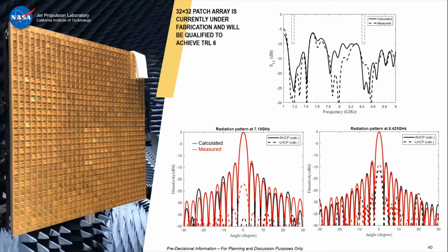We did not see any discharge, or the only discharge that they saw, they couldn't tell if it was only noise or actual discharges. That was actually the first time ever that they tested a piece of hardware and saw such low discharges, and that's why they couldn't tell if it was noise or not. So our antenna is ready to go to Europa. We reached TRL6, which stands for technology readiness level. Whenever we go into flight missions, we want to be at TRL6 to move forward with the technology.